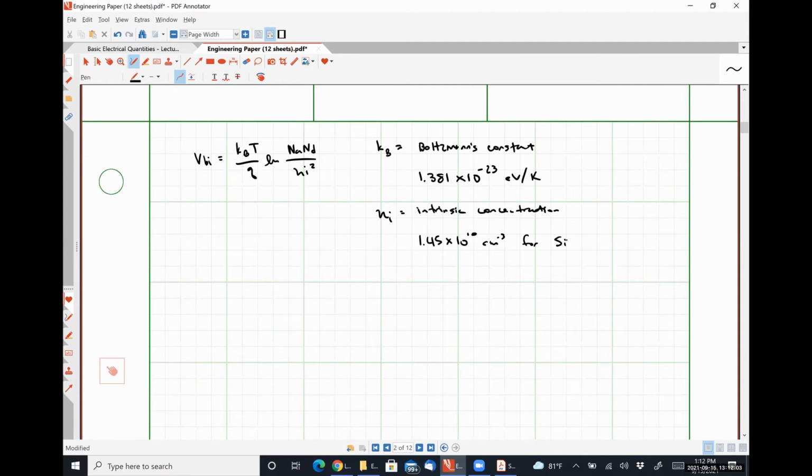That cannot work that way, not on this small of a scale. That type of junction can be loosely approximated by what's called a step junction, a specific way of doping the crystal to cause an almost perfect transition between the n-type and p-type material, where the concentration throughout the n-type is one thing and throughout the p-type is another.